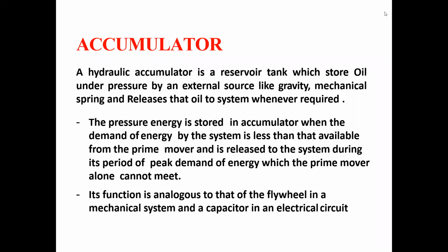At this time, the high pressure fluid stored in the accumulator is used. How are we going to store this high pressure oil? We store it using sources like gravity or a mechanical spring. How we use gravity to store the high pressure oil, we will see further in today's concept.